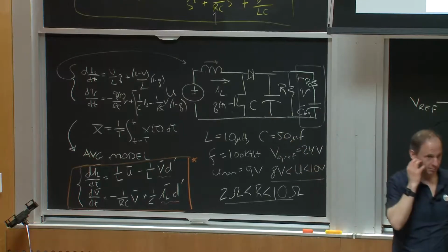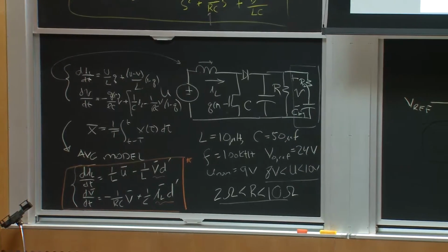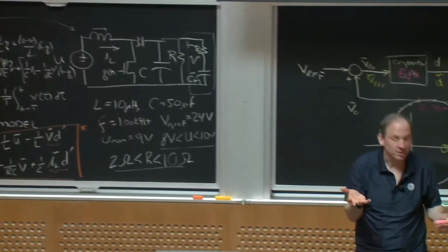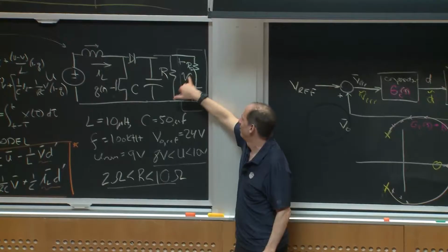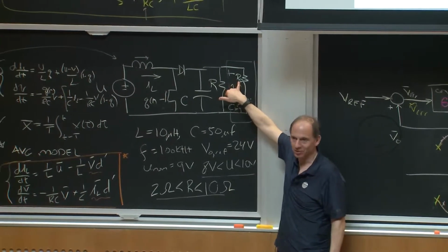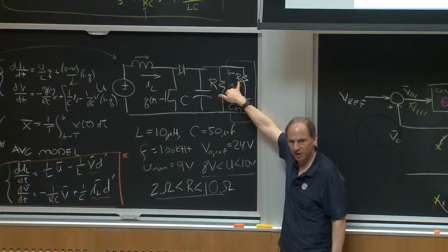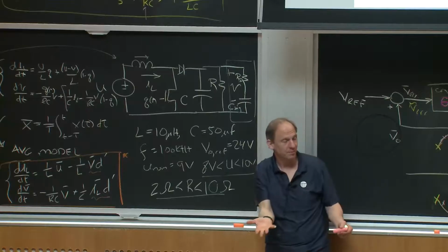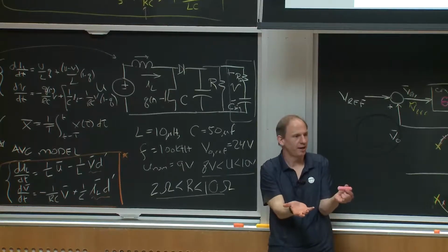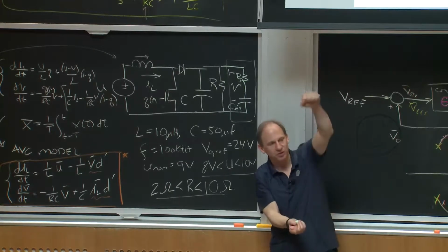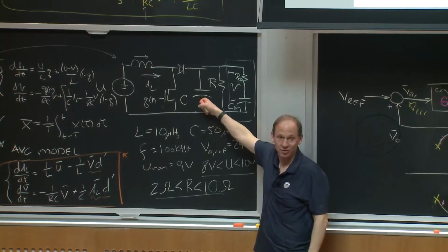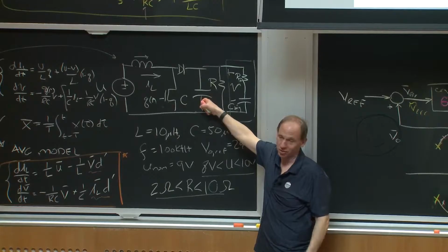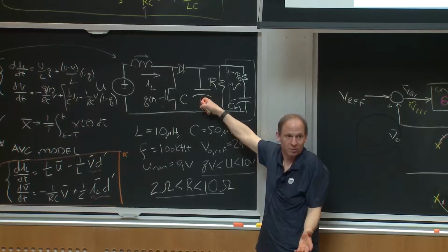Nothing wrong with that. Do it all the time. The upside is it works. The downside is now I've got to go out and buy an extra capacitor and a damping resistor. It's more expensive. There's some things you can't change, though. Some things you must change in the plant. If I want to reduce the amount that voltage is going to swing up when the load steps down, I'd better go get more capacitance. There's no way around it, because there's nowhere else for the energy to go unless I'm going to somehow dump it.